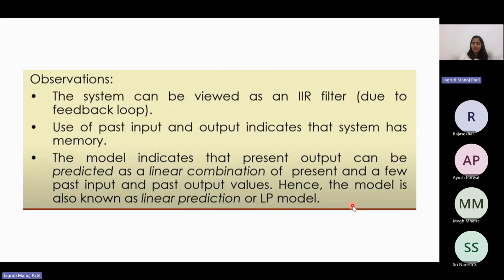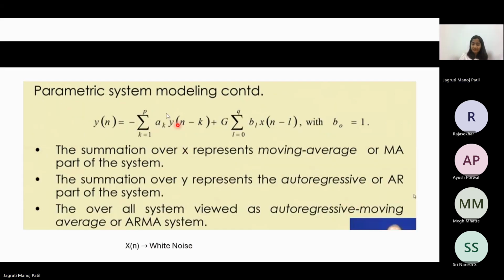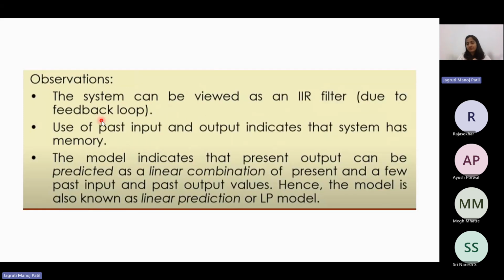So the linear prediction model can also estimate based on the past input value as well as the past output value. This is your past output value, this is your past input value. Accordingly you can change this and modulate your present value. This autoregressive moving average filter is kind of nicer, but it's also trickier to implement. I did my project with one of the professors from here.